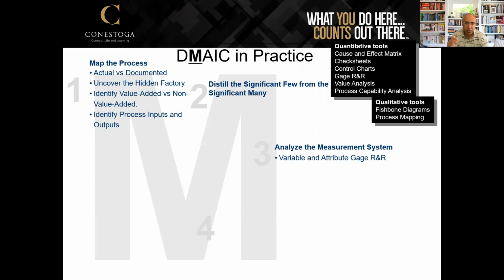And you want to make sure your measurement system is proper. If you're using any equipment, you want to make sure your equipment is calibrated properly. People know how to run the equipment. Otherwise, your data will not be valid and your data will have problems. So that is what the gauge R&R is for. There's a methodology to make sure your analyzing system is correct. Otherwise, if your test equipment is not calibrated, your people don't know how to run the equipment, then you will get different results.